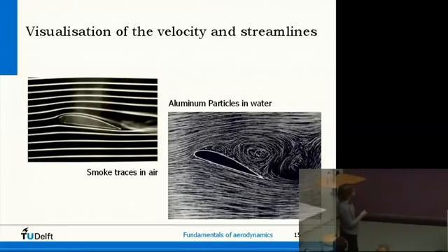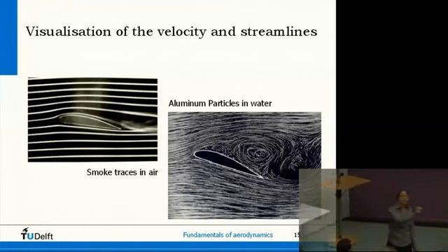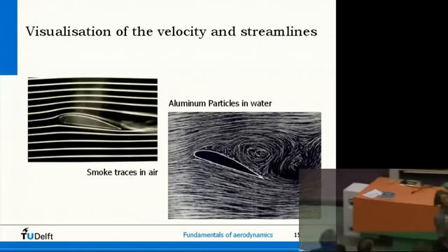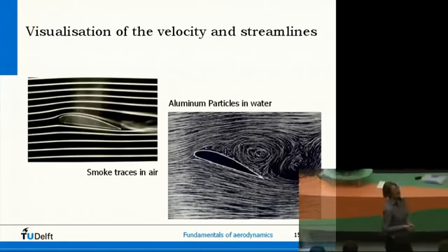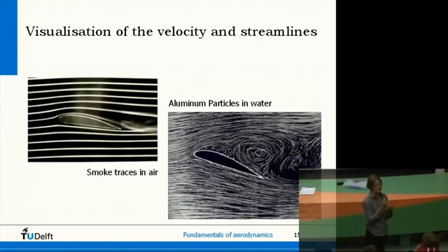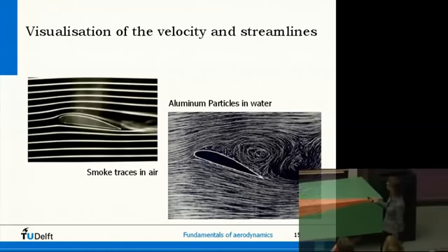So you see that the flow follows the airfoil, but here something interesting happens, right? Something blurred actually happens. Instead of a nicely smooth smoke pattern, you get this blurred smoke pattern, and that is due to small vortices. I will teach you later about viscous flows and turbulent flows. So you get transition to turbulence, and you can even get separated flows. All kinds of vortices happen, and you can actually visualize them in the wind tunnel like this.